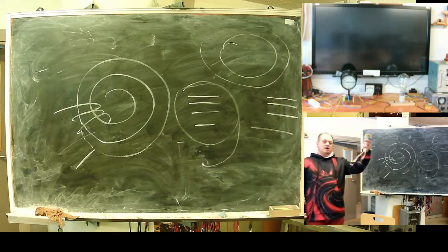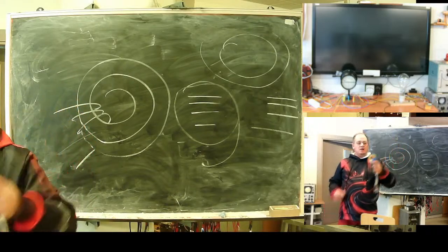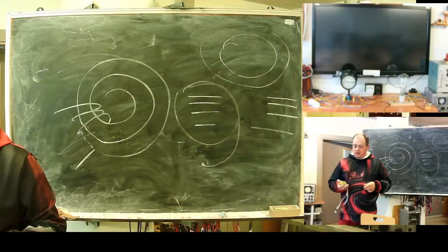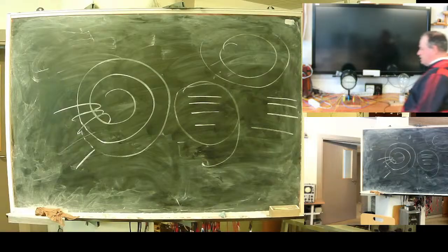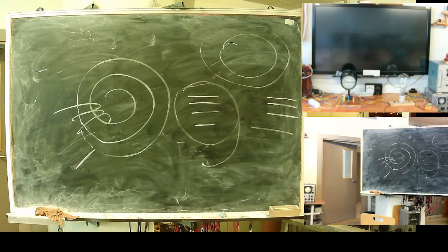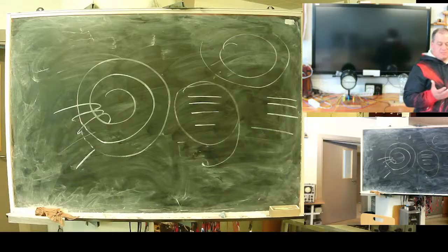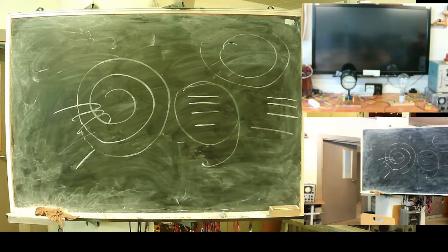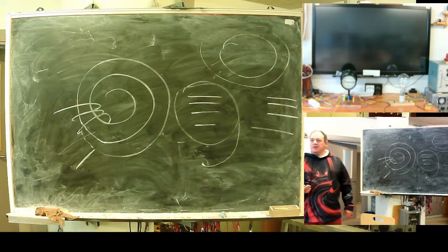I have one here, it's a current transformer, but inside is very suspicious. The cheapest version of such transformer is made on powder core. Plastics mixed with magnetic powder and pressed together to form a ring. You can feel them by weight, they are lighter.